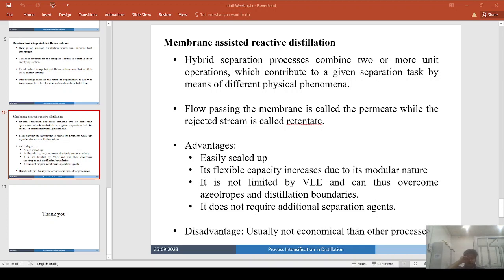Now let me briefly discuss reactive high gravity distillation, or high G distillation. As we have discussed, high gravity technology, or high G technology, replaces the usual gravitational field by a centrifugal field achieved in a specially shaped rotating device. The high gravity field of about 100 to 1000 Gs shifts the flooding limit and allows the use of dense packing material with a high interfacial area.